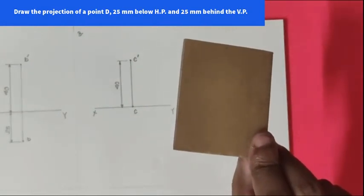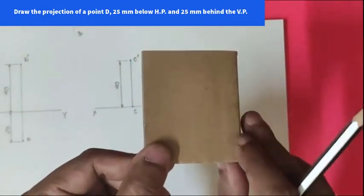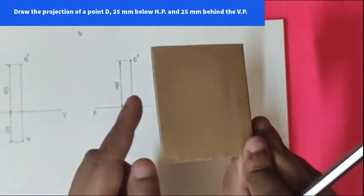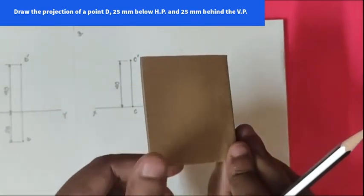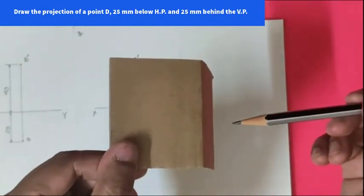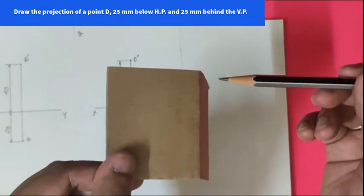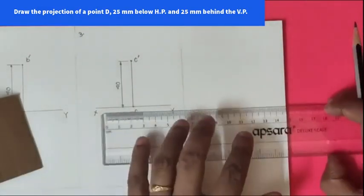So for the third quadrant, let us draw the front view first. For the front view, how far is it? How far below the HP? This is 25 mm below the HP, and we are viewing from this side. So it will be projected where? In the vertical plane. That means below the XY line. So let us draw.